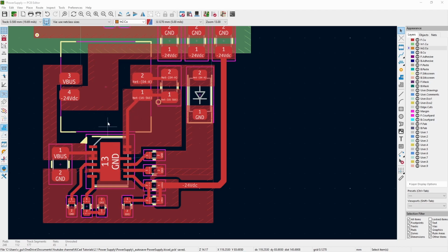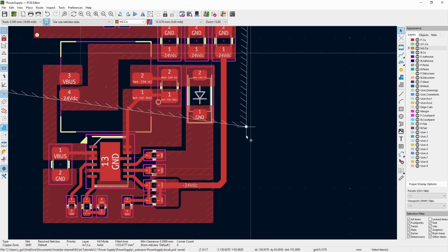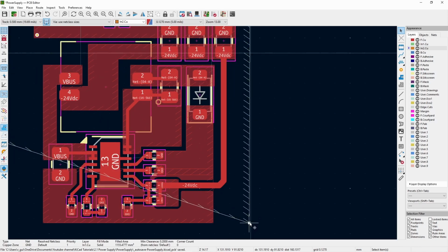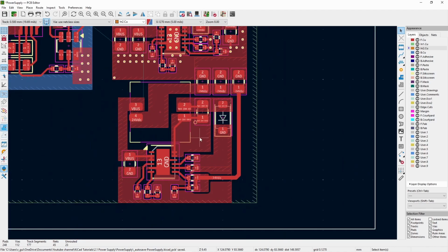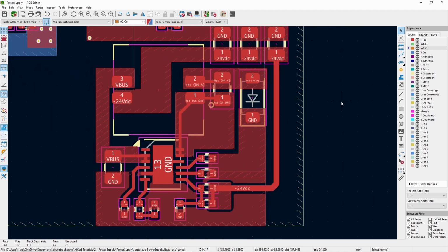I don't want to take it down through the ground path here because I want to have some wires on this section so that I can connect the chip and the ground to the ground plane, which is on layer 2, the green layer that you see here, which will extend down all the way to here basically. I've got a few more episodes before I order this, so if you have any feedback for me, please let me know.